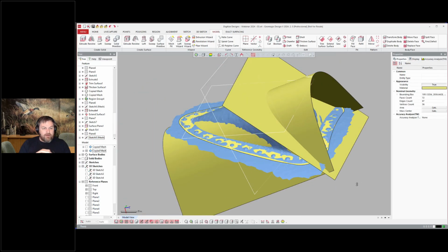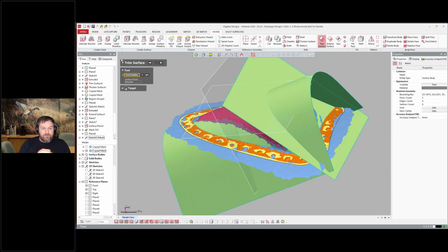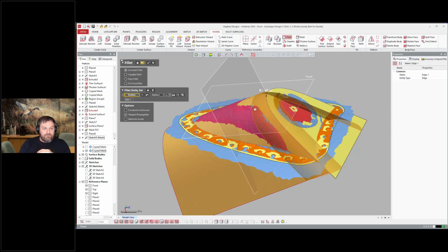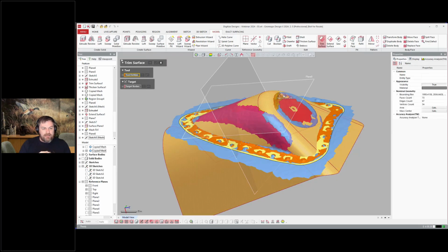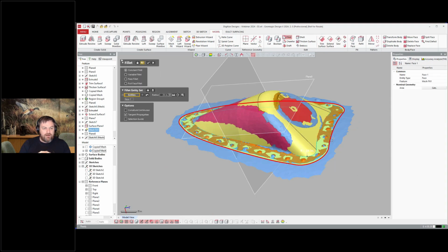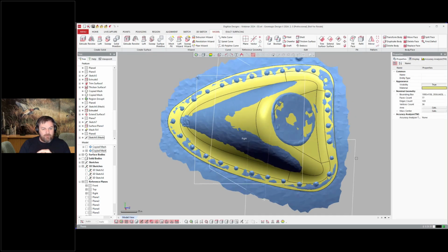So you see, now I'm going to go into the trimming phase, where I'll go ahead and trim those surfaces together, add a fillet there, and then trim all of these together from there on out. So you see now we just trimmed all those components and added some finishing features like fillets and stuff there to create that panel, so a replacement panel for that side.